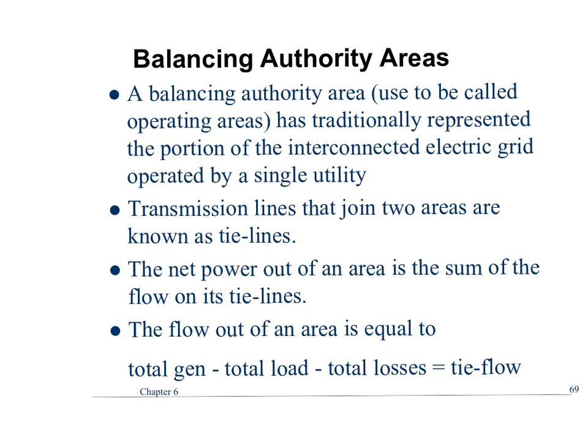upon. If it's not, there's something called automatic generation control that'll bring things down, and then either the company or the utility that's responsible for maintaining their power that's too low, they'll have to kind of come up with generation elsewhere, or it'll get choked offline. How do they choke it offline? They start to decrease the voltages at the bus that's near the tie lines, so they actually can monkey with it.